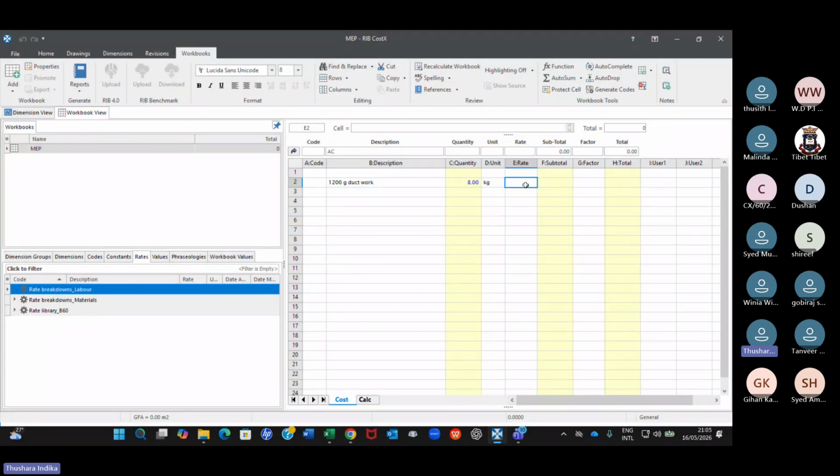So it is the same principle. What I give you is a principle, basics. I don't want to measure a complete building with you guys. That is not the point. So I give you the principles, then you can apply those principles anywhere you want. I have shown you how to do the linear measurement, the square meter measurement, and the counting, and then how to feed into the BOQ and how you can manipulate heights and so on. So all I have taught you.